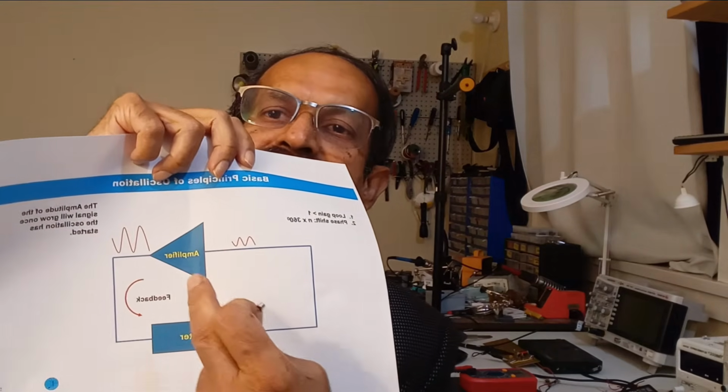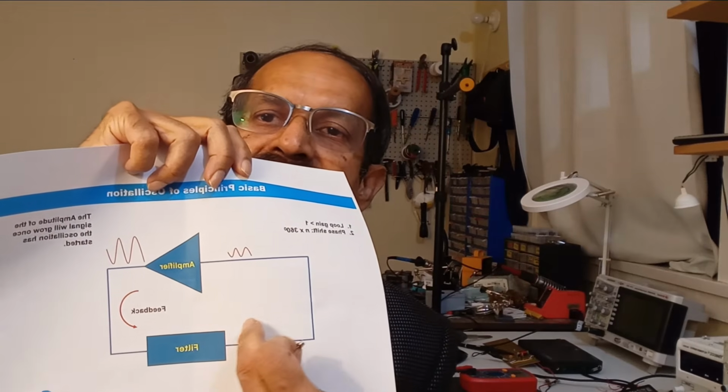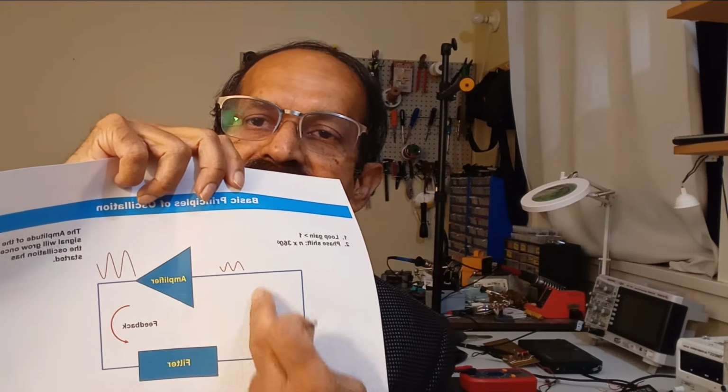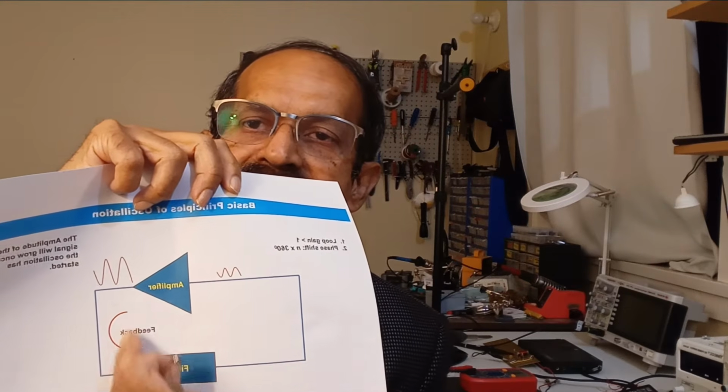Hello everyone, today I'm going to show you how you can make a quartz crystal oscillator using a MOSFET and few other components. Every amplifier can become an oscillator using a feedback circuit. Here I am showing you a block diagram, amplifier with a feedback circuit, and there are some certain conditions this circuit can oscillate. So at what frequency the oscillation will happen depends on the frequency selective response of the feedback